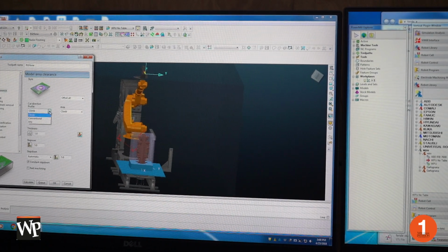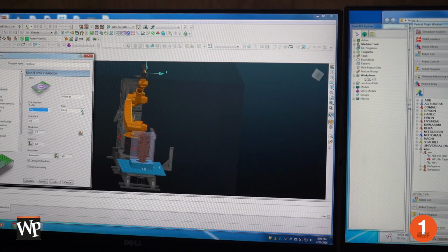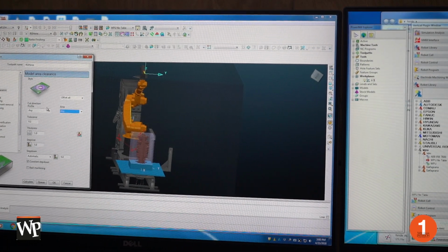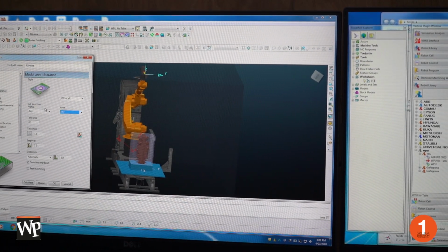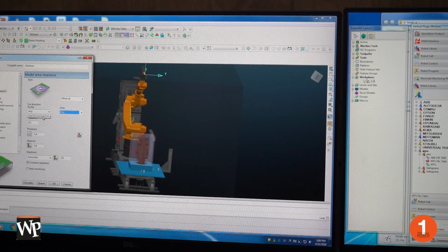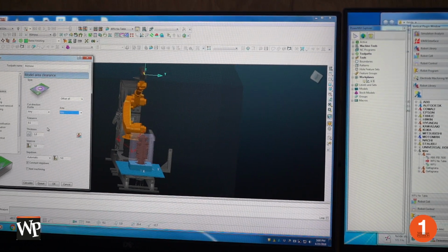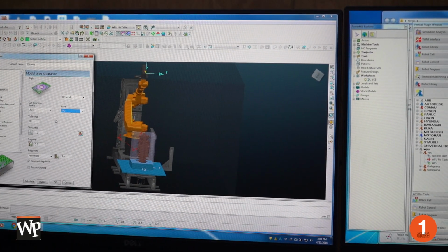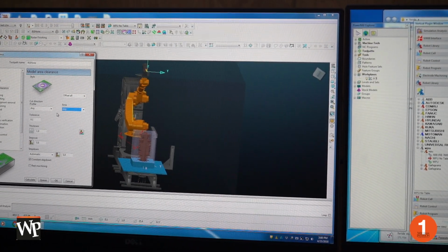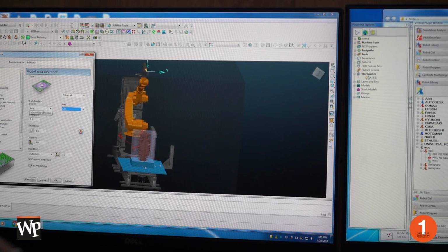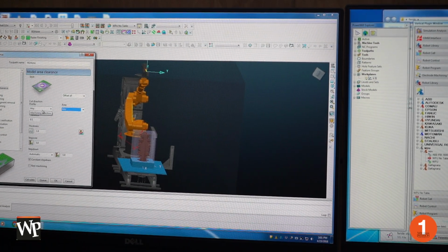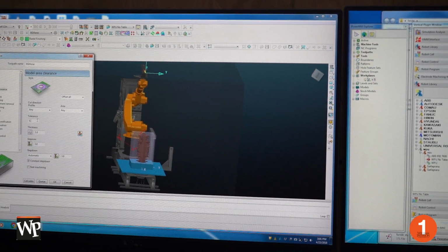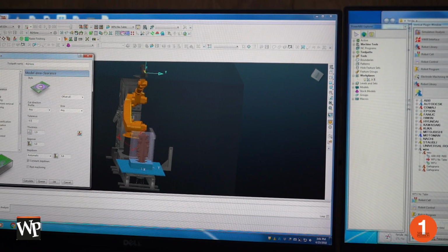Cut direction, we're going to choose any for the profile, and area any. This will be determined by our material, and since we're using foam, we can do any and any. When you have material that has a grain, like certain woods, harder woods, or if you're doing metal or stone, you want to maintain a certain direction with your cuts. Our tolerance, I'm going to move to 0.5.